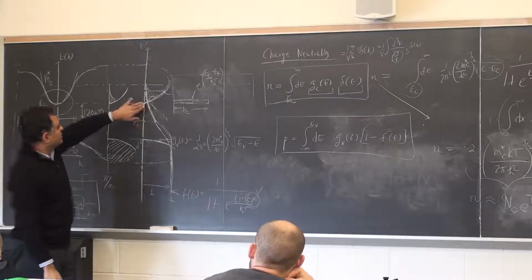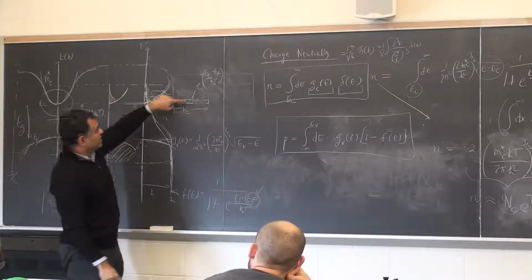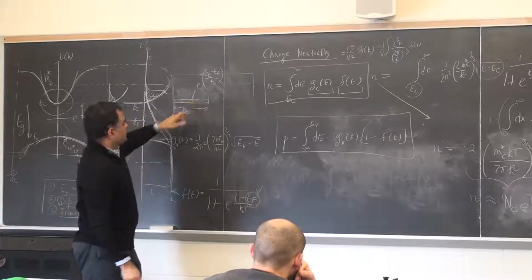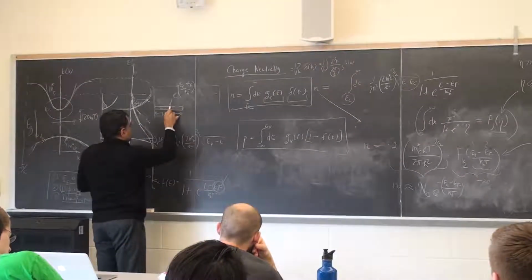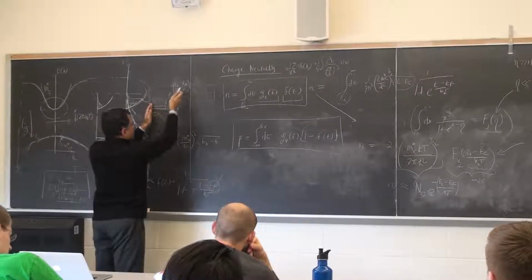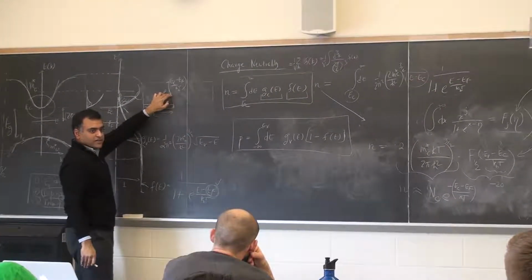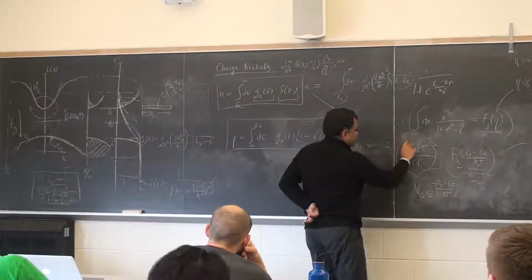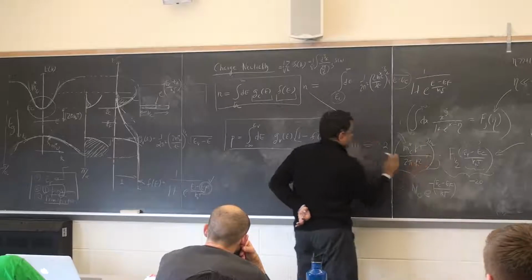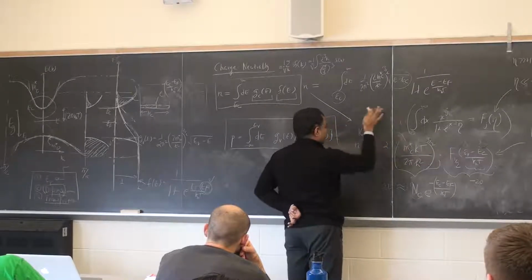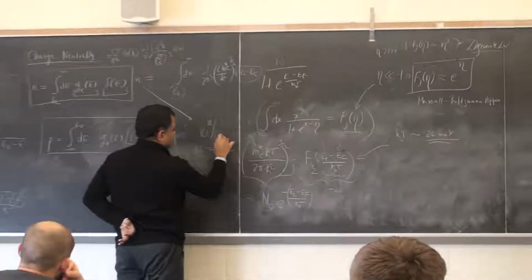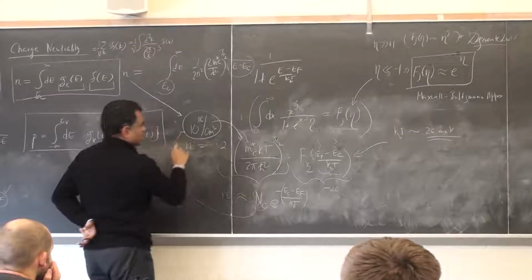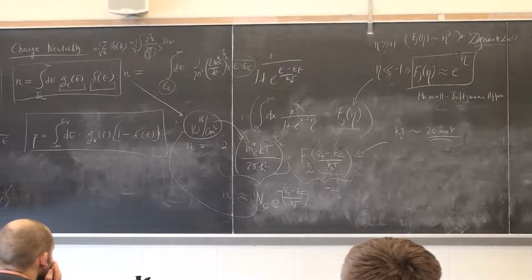Physically, the reality is something like this, and this approximation, the non-degenerate approximation, makes it look like I have a constant DOS, and if I want to find how many states are filled, that's the factor. Does that make sense? If I substitute typical numbers of, say, 0.2 effective mass, room temperature, and Planck's constant, you will get something of the order of 10 to the power 18 per centimeter cube. This NC is of that order, 10 to the power 18, maybe 10 to the power 19, depends.